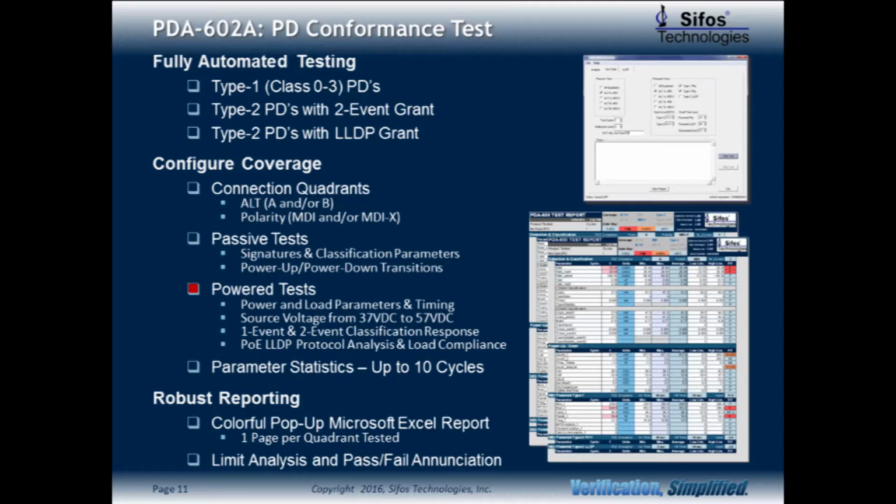Powered tests cover initial and steady-state loading, responses to single versus multi-event classification, and, if specified, PoE LLDP protocol behaviors and responses to LLDP dialog with a PSE. Testing may be automatically repeated up to 10 cycles for the purpose of evaluating parameter repeatability and capturing rare intermittent behaviors of a PD.